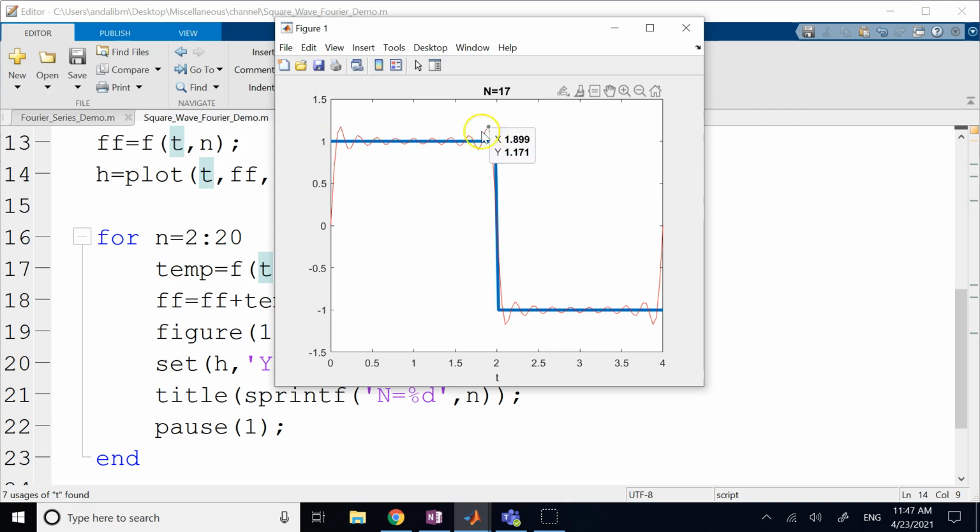But this sudden change, this step-type behavior that the approximation shows, is getting closer to what? To the original step-type behavior. Okay, but at the expense of getting more and more ripples, because you have more and more frequencies added to your approximation. Now the question is, how far should I go if I want this red curve, which is the approximated function, to perfectly match this step-type behavior?